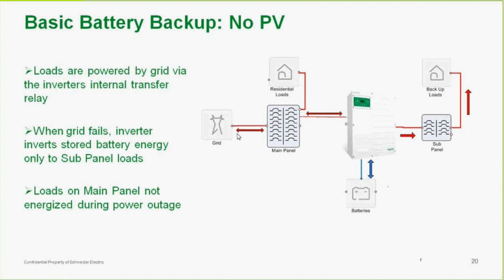Now, we can use multiple inverters, but generally speaking, in my opinion, a good battery backup system covers your basic requirement loads and not the big ones. It does require pulling a sub panel, which I know is electrician time. It's $1,000 to $2,000 in labor to pull a sub panel and bring those loads over. And it's never simple because the house was not designed originally for that. I understand that, but it is the best way to do it.